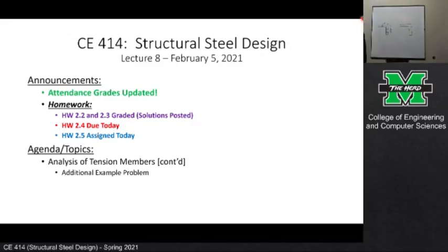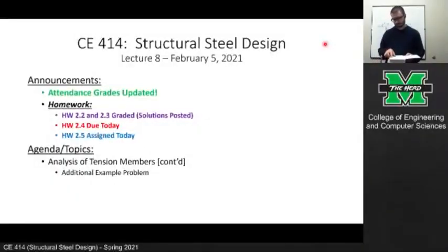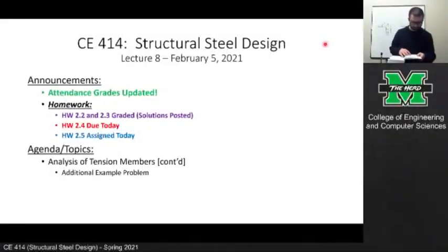Now, there was another hand raised. I think that was Mr. Adkins. Did you have a question? I was looking in the steel manual here. It was related to the 80 ksi part of the tensile stress. Yeah, I'm going to pull my steel manual up right here. Go ahead. According to the manual, for wide flange shapes with flange thickness over 3 inches, only the minimum of 58 ksi applies. So, in this case of the tensile stress, we should stick with 58 no matter what.